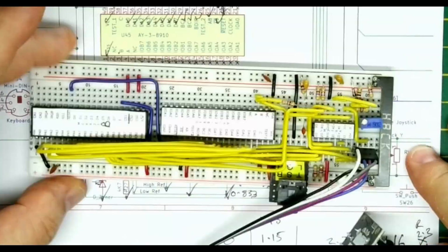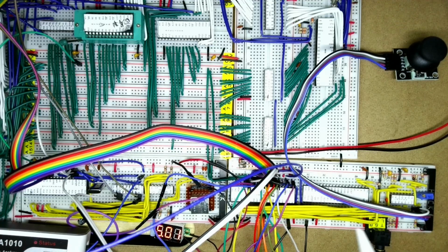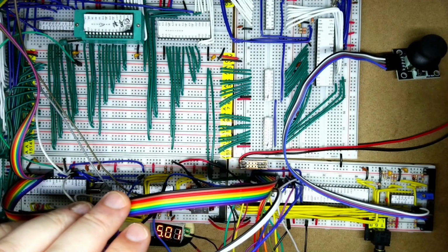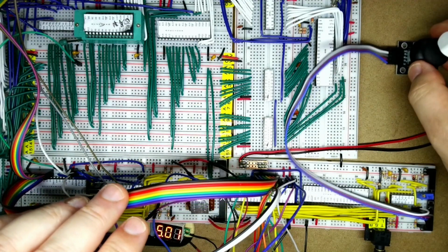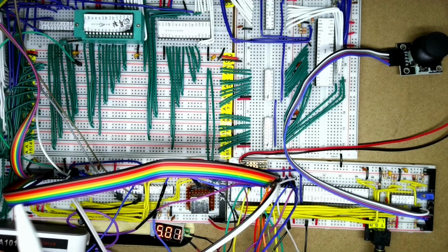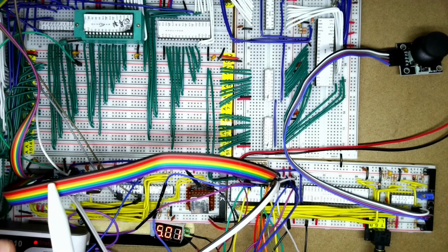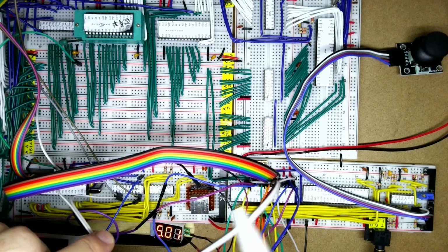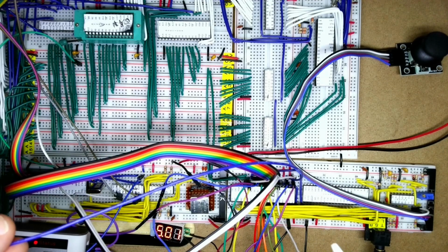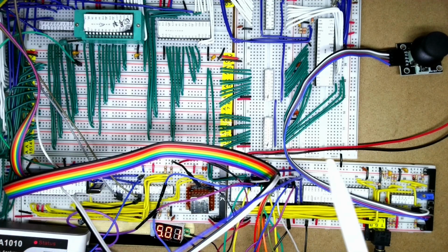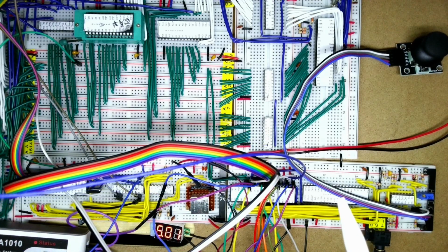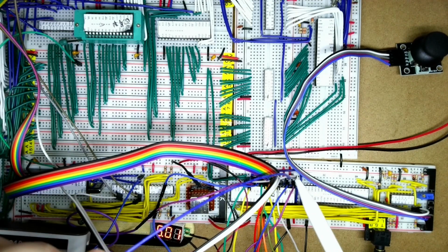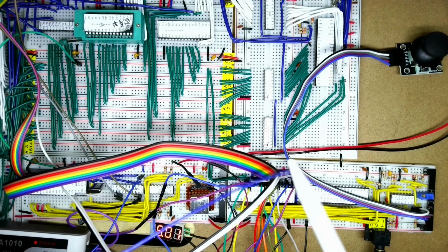Check that off. Okay, so you can see here I've hooked up the programmable sound card and the joystick, which is plugged in over here. All I've done is piggyback it off the keyboard controller that we did in the last video, so it's basically the data leads, reset, read write, the E signal, and then we've also got the CRTC address enable 5 output, which is going to our chip select low there. So that's plugged in there.